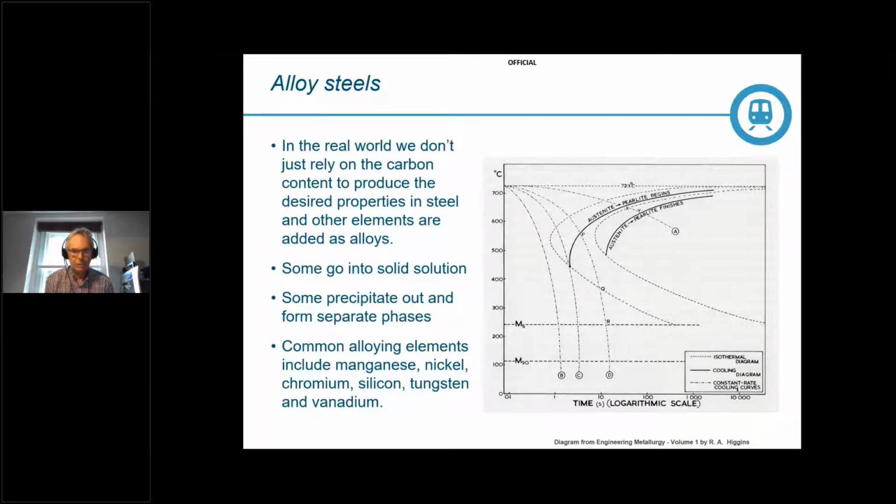And this was used in the past, both for rolled rail and for castings, but it's now only used in cast crossings. In this, 13% manganese is added, and this allows the austenite, which is normally present in the molten state, to remain stable at room temperature so that it does not transform into ferrite, pearlite, or martensite. In fact, the upper critical transformation is depressed to below room temperature.